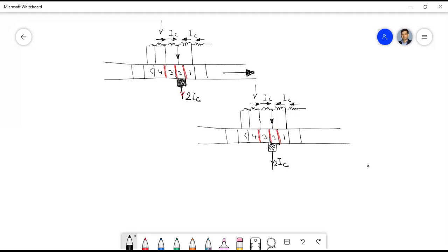But there will be some current in this, because you see the brush is now in contact with commutator segment 3. So some part of the current will be diverted to this 3, and this 2 also. Previously, 2 was sharing 100%. Now the share will be a little with the 3, isn't it?